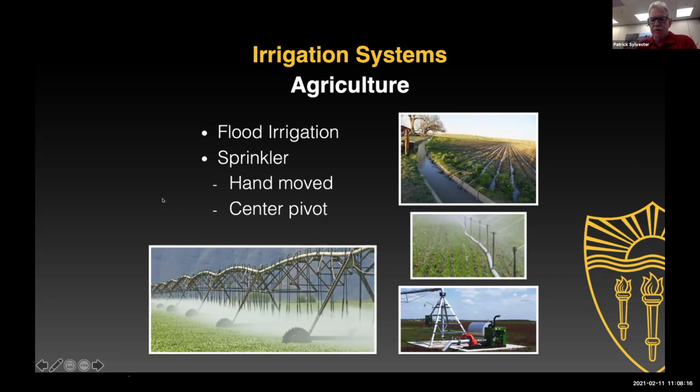Again, if you're using well water and there's no interconnection between the well water and the potable water system, if you're talking about protecting your potable water system, then you don't really care. If there is well water and you've got your potable water system attached, then you're looking at protection simply because they've got well water there, where you don't have control of the quality of that water.